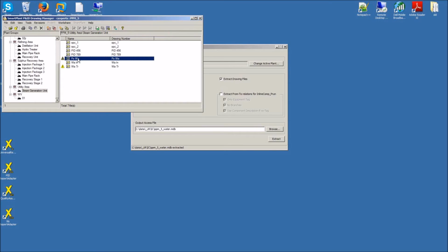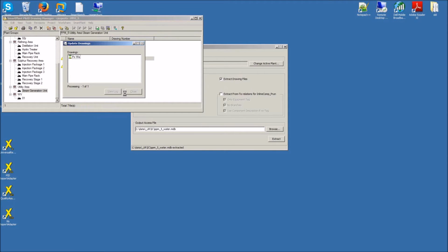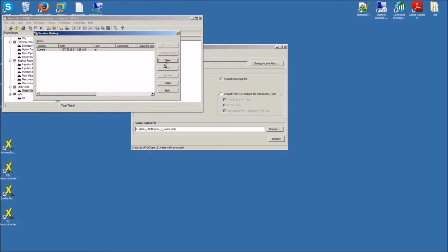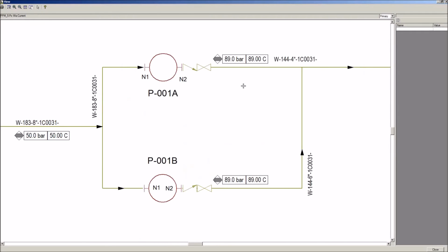I'm going to update the drawing so that the API modification will also be placed in the graphical labels. This is a function that is used by many P&ID users on a regular basis. And if we have another look, we can see that the values were also changed on the labels, and the change is coming from Universal Reporter.